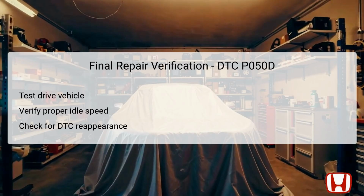It's important to pay close attention to how the vehicle behaves during cold starts, ensuring that the rough idle and stalling issues are resolved. During this process, continually monitor for any reappearance of DTC P050D using the HDS. Confirming that the error code does not return will affirm the success of the troubleshooting and repair efforts.